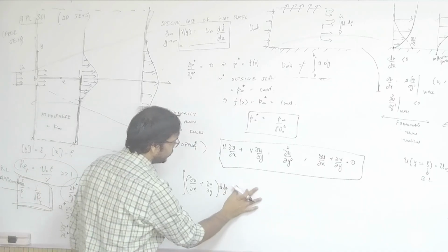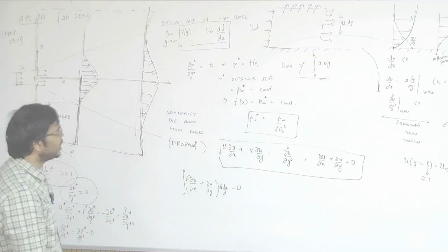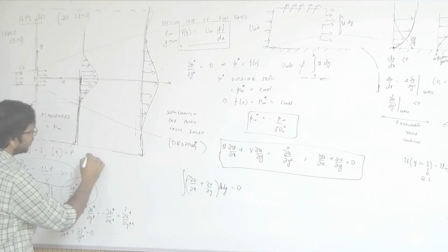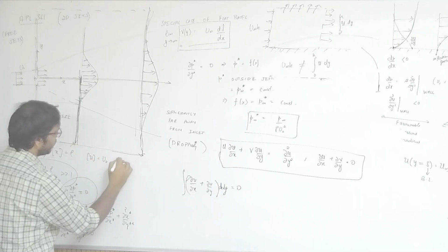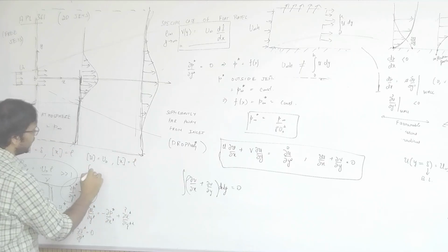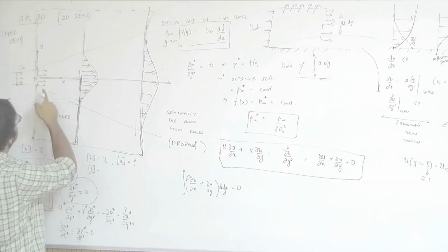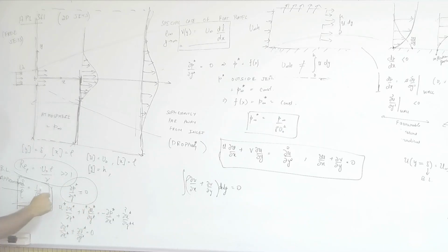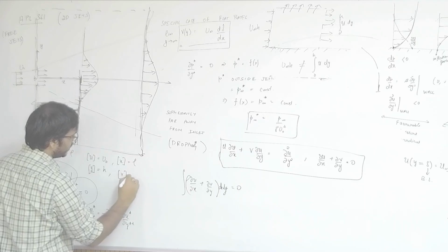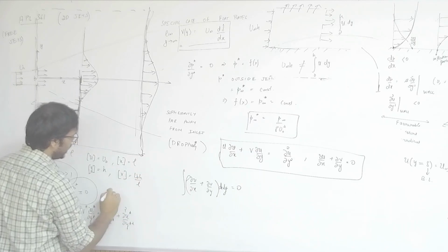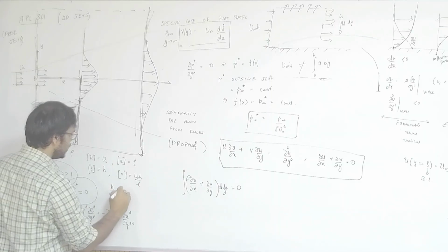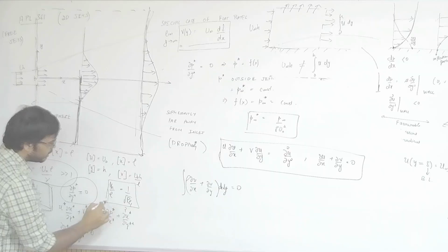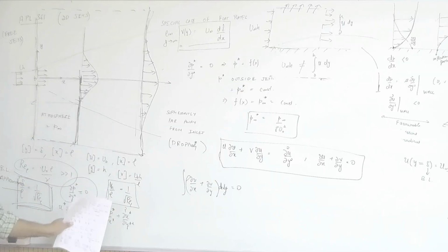That is what we are doing, integrating the continuity equation over the control volume. Our velocity scales are something like this, and we can take a y scale, which is, let us say, h here. Given this y scale, the v scale is going to be u naught h over L, and we are in the zone where h by L is equal to 1 by square root of Re_L.